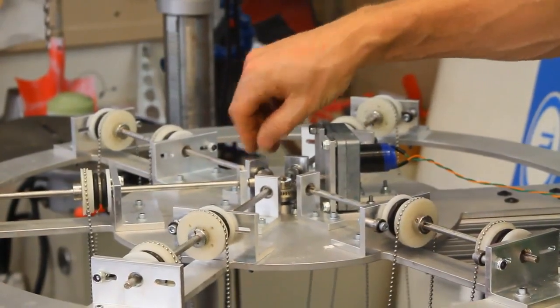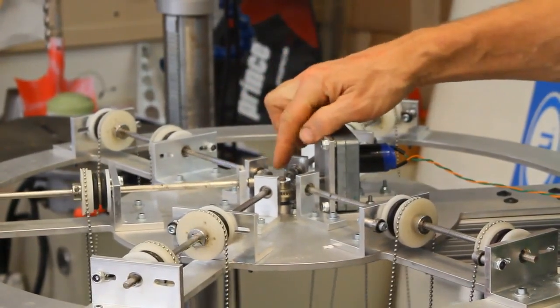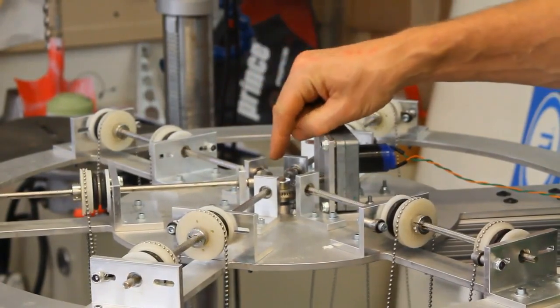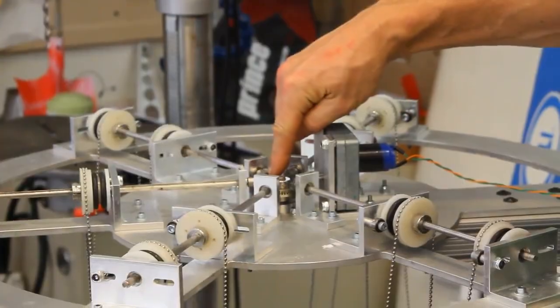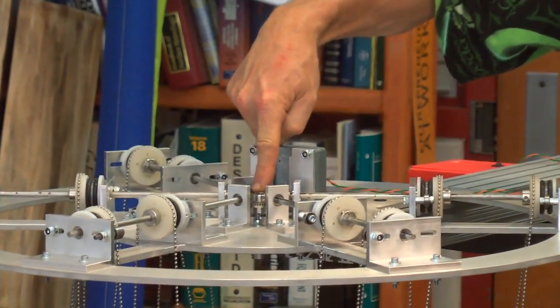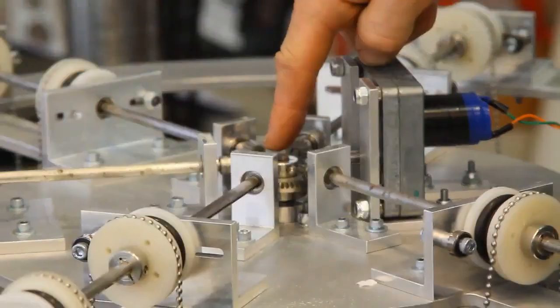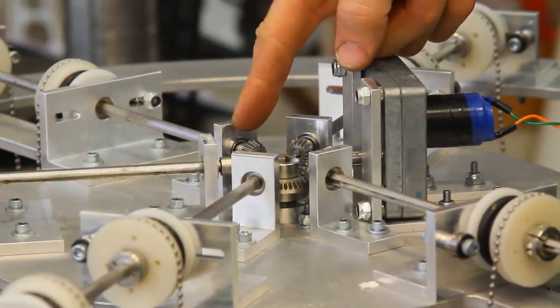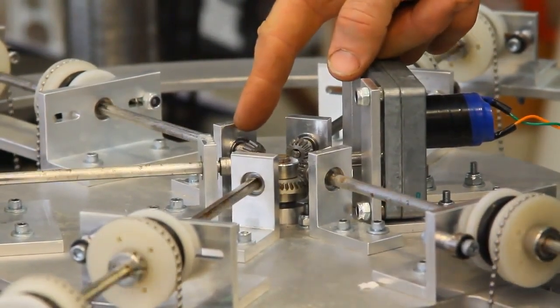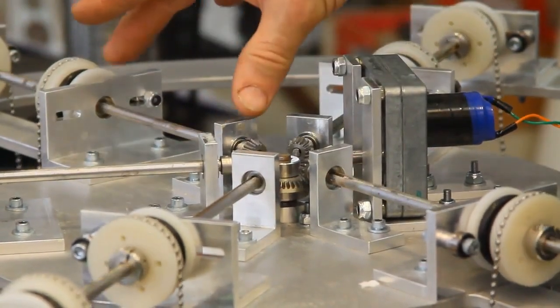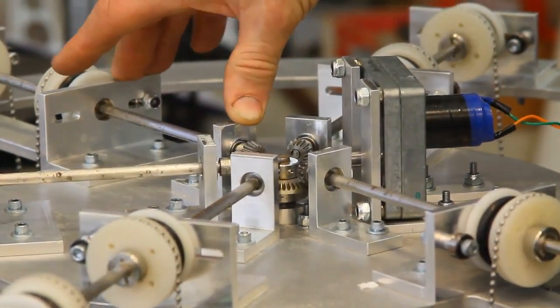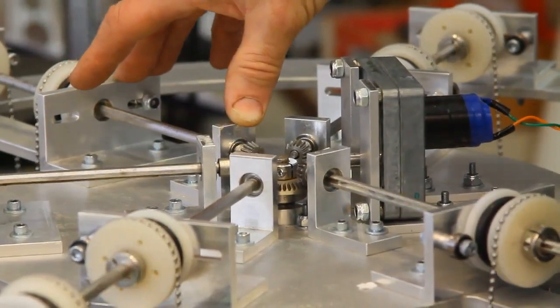So in that case, the hub would extend in the middle. Now, sometimes there's no room between the front face of the gear and the shaft that it would otherwise intersect, and you have to put the hub behind. You just have to do that sometimes. You don't have the space. But then you calculate the gear tooth separation forces, the bending of the shaft, loads on the bearings, and you can sometimes tolerate that.